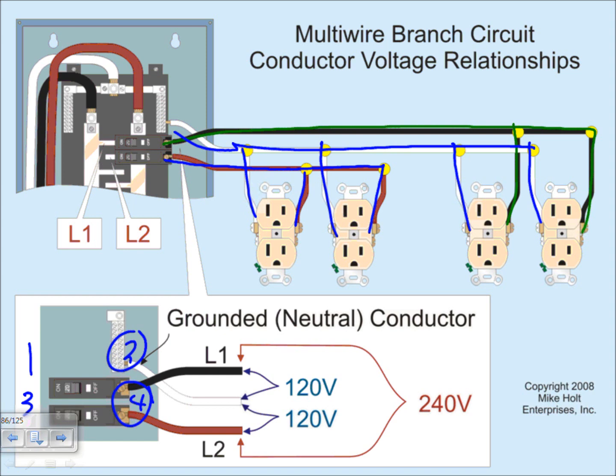If I want to make this three-phase, all you have to do is add a third one here. The voltage that we use in the US for three-phase becomes 208, and this voltage actually continues to be 120, because these are the utilization voltages. Here's a multi-wire circuit, multi-wire because they all share the same neutral. You can only have up to 3 hots with one neutral. 4 hots with one neutral? No. Feeders, branch circuits, and service: always up to 3 hots with one neutral.